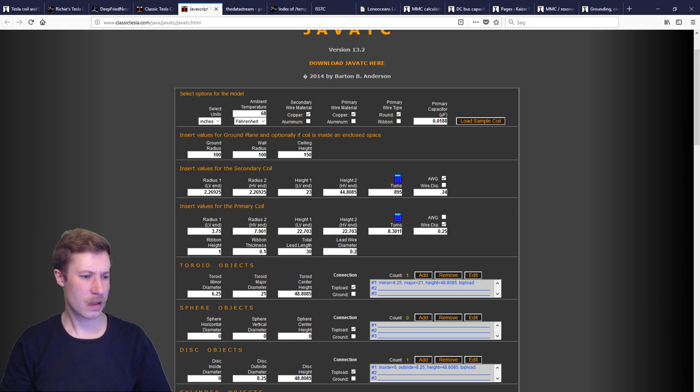Okay, experimenter has a question here. He says, I measured the resonance frequency of my secondary plus top load, and it is around 75 kHz with simulated spark loading. Should I tune my primary circuit to exactly 75 kHz or lower for perfect tuning? I have done a few experiments myself with the simulated spark loading simply by putting on small pieces of wire out from my top load. That will have the almost exact impedance and capacitance resistance as a spark, and I still find that the result is misleading.